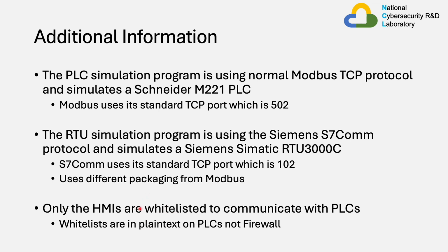Only the HMIs are whitelisted to send packets and communicate with PLCs on Modbus TCP and S7COM. Any other packets with the PLCs as the destination will be ignored. This whitelist is on the VMs controlling the PLCs and not the firewall. So the packet is ignored after reaching its destination PLC and is not dropped.